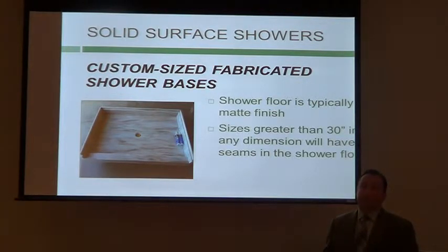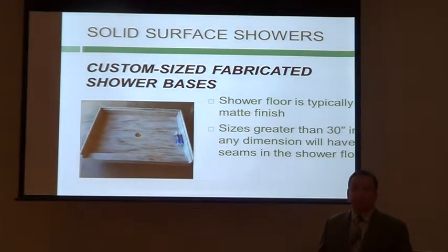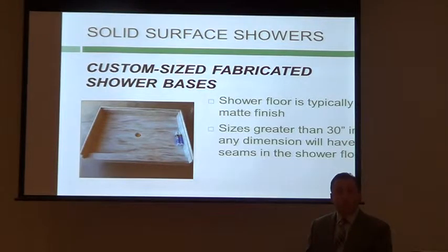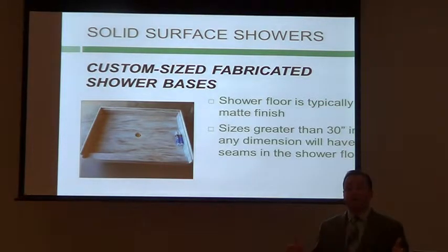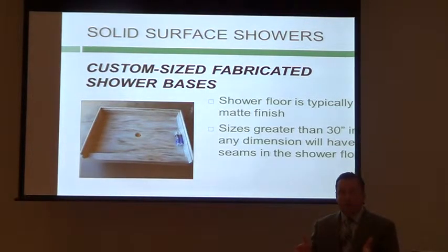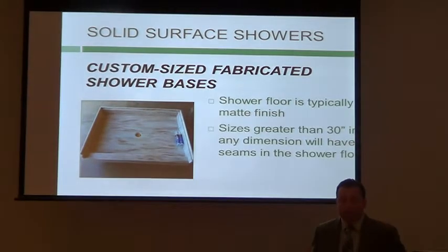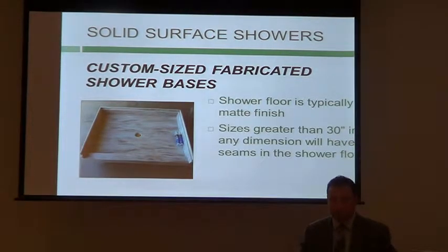The solid surface industry was based on the fact that it's a relatively expensive material. We don't want too much waste, which adds cost. We don't want a lot of scrap or cutoffs. So let's make our sheets 30 inches wide. It allows the fabricator a huge advantage. Here's how. If I take my all-American kitchen countertop, let's just say it's 25 and a half inches deep, I make two cuts, two rips, lengthwise down that panel. I cut a 1-inch piece off the front side, I roll that down and glue it, that's my front edge.